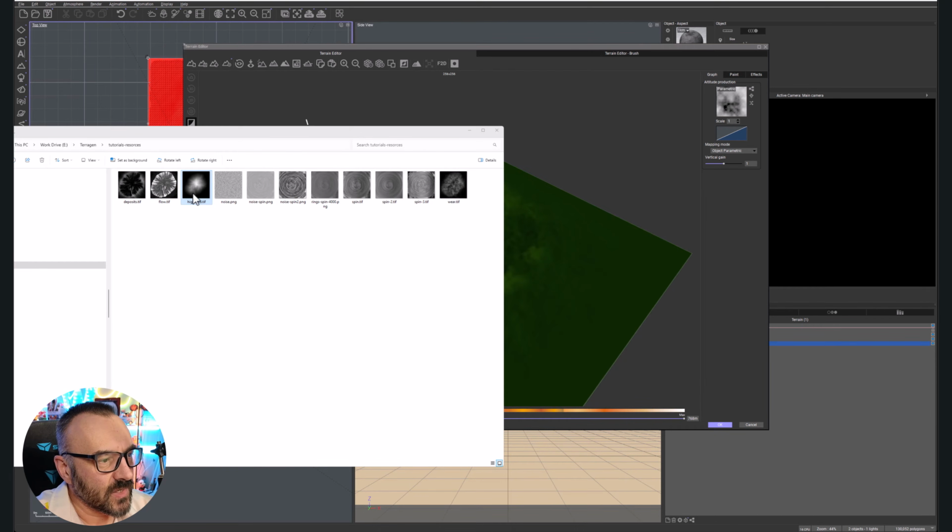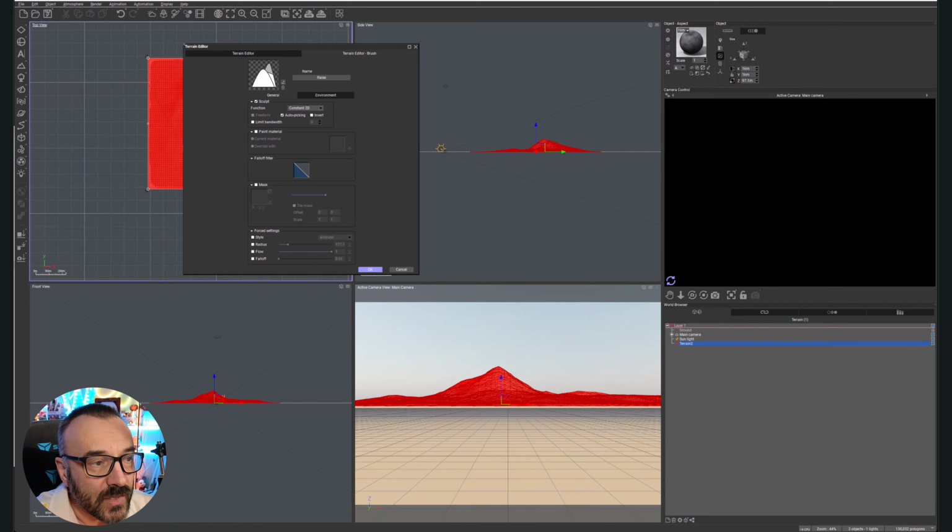Now we can check right here. You can see there's our Highfield, and if we hover over it, it says 4,097 by 4,097. So we're going to use this image as a height map. And notice we have all these different maps. These maps were generated with World Machine. I have plenty of videos about this. You can check them, and more of course will be coming up. But what we have here are design, deposit, flow, and Highfield. Those three we can use, and you'll see how. But for now, this Highfield we're going to use to control our terrain.